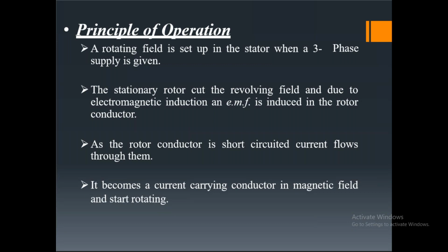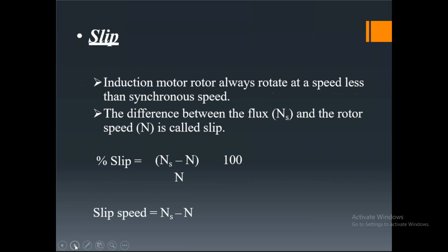So when we apply the supply to the stator, it will produce the field, and this field will be cut by the rotor conductors and EMF will be induced. Due to this EMF, current will flow in the conductors, and then it will rotate. So this is the principle of the motor, and it is very similar.